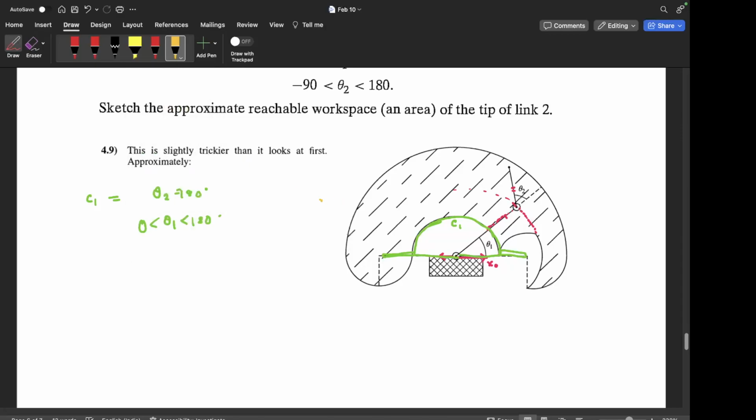the very outermost one. Again, these two are the ones which we have seen in our drawings of the 2R manipulator workspace. So this outer part till here, till 180 degrees, till here. So this is the case in which theta 1 is arbitrary and theta 2 is fixed at 0, the full extension case, right?